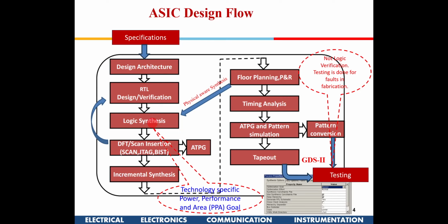Each gate is going to be technology specific. For an OR gate, from the fab lab they might give you several kinds of OR gates, which are low power, fast, and things like that. Also a certain circuit can be implemented in multiple ways, and that can affect the gate sizes. A bigger current carrying capacity OR gate could be there, or a lesser current carrying capacity OR gate, which will make it faster or slower, or high power, low power. So all those variations are possible.